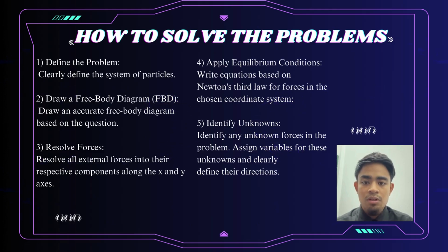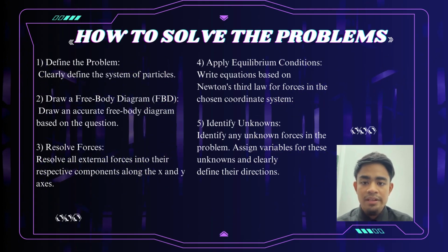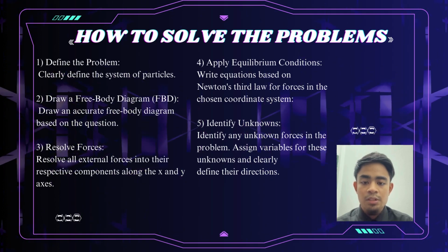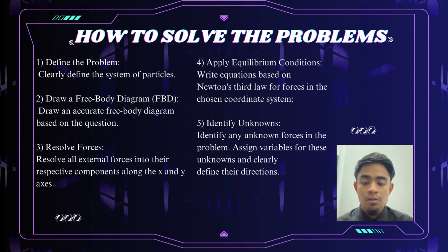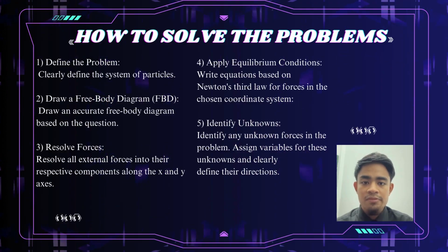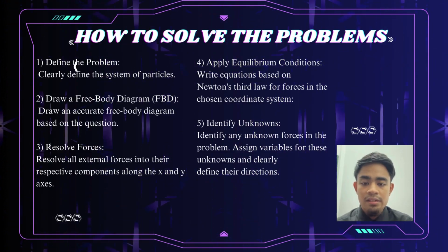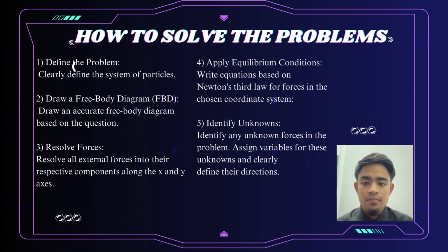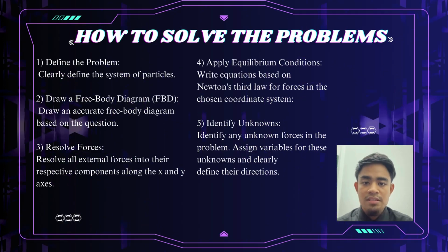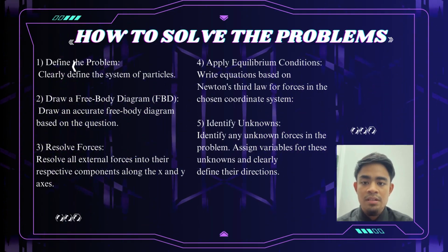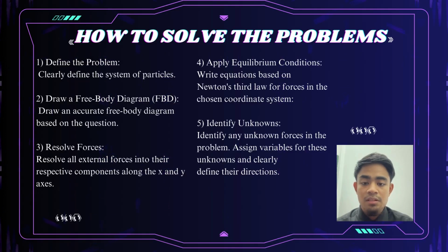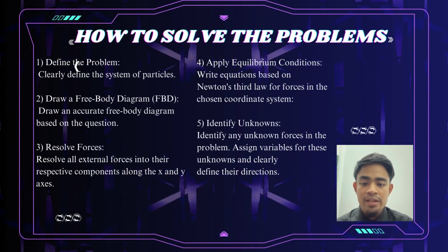We need to draw an accurate free body diagram based on the problem. Also, we need to label each force and its direction. The third step is to resolve the forces. We need to resolve all external forces into their respective components along the x and y axes.